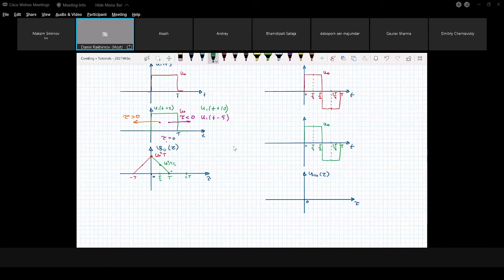But then if you go to the second half, you have a negative rectangular pulse times another negative rectangular pulse. Minus times minus gives you plus. As a result, for the second half, the integral will again be u0 squared times t by 2. And the total integral will have value u0 squared times t. The same result.